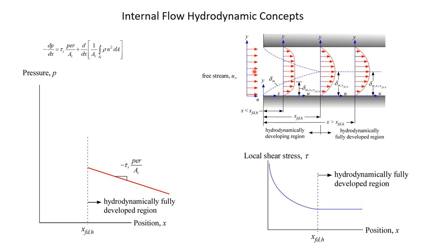So in terms of velocity squared, the center core here is going to increase in velocity squared by more than the edge decreases in velocity squared. The center core increases in velocity by about the same amount that the edge decreases in velocity, right? Because that's what continuity is saying. But in terms of velocity squared, the center core increases in momentum by more than the edge decreases in momentum. So all that says that the momentum of this distribution here is greater than the momentum of this uniform distribution here. And so you're increasing the momentum as you move through that entry length, right? And so this term is actually positive as well.